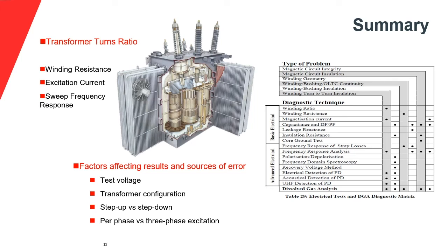I should say, I haven't mentioned it before, but when you decide to do a step-up measurement, you need to make sure that you are using the proper instrument to do so. We are trying to induce a higher voltage than the one that we are applying.